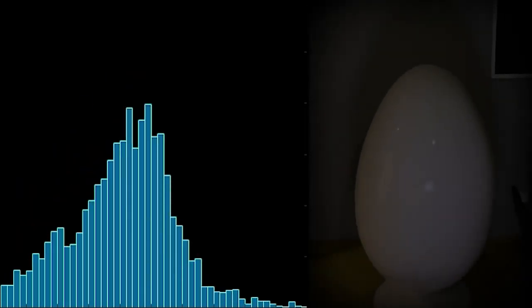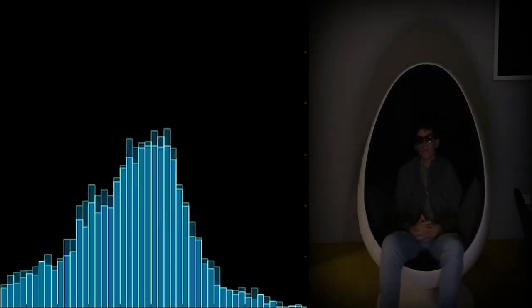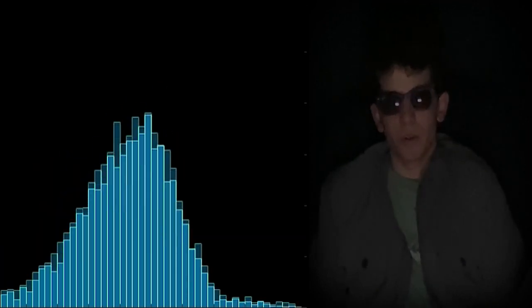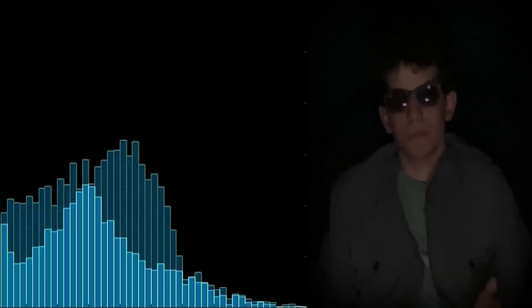Our aim was to visualize music using MATLAB. In this video, we'll explain how we did that to create the moving graphics that you can see on screen. We wanted to visualize the audio by looking at it in the frequency domain. In order to do this, we take the Fourier transform during a small time frame window and plot it.